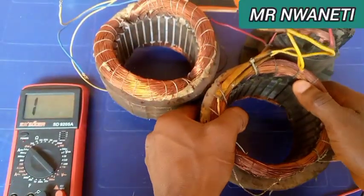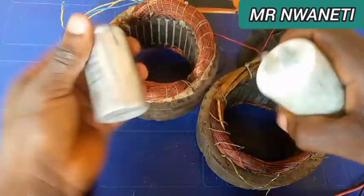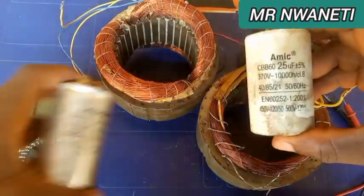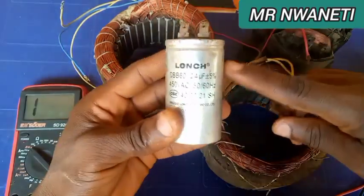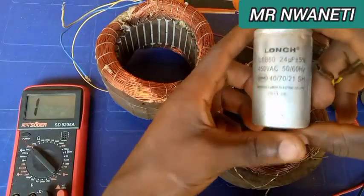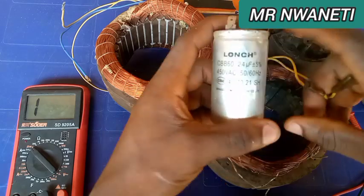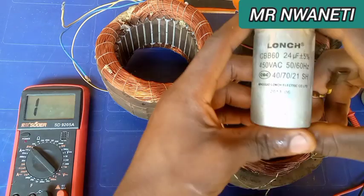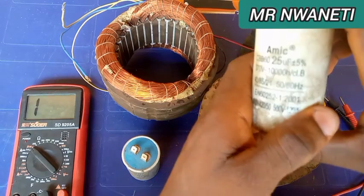Another thing I want to display: assuming you are getting 200 volts. These are two capacitors. Assuming you put a 24 UF capacitor and you are getting 220 volts and you want to get 230 volts, and you don't want to tamper with the winding, then what you have to do is go for 25 UF or 30 UF.